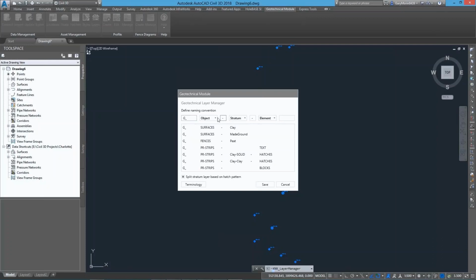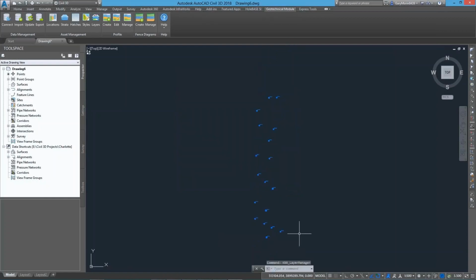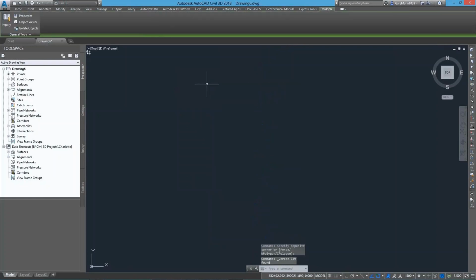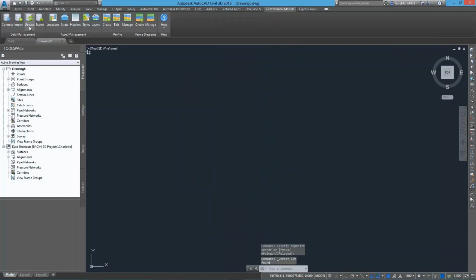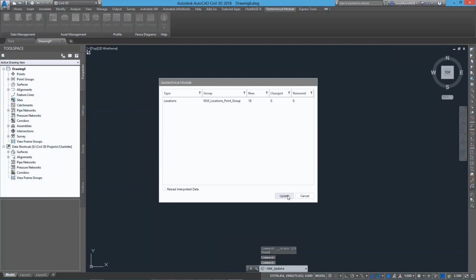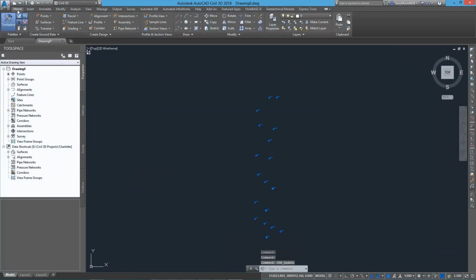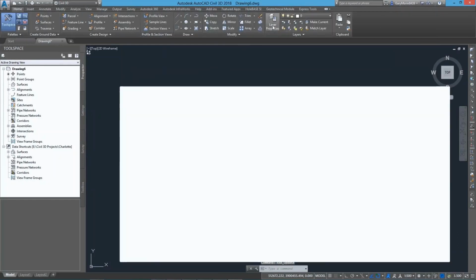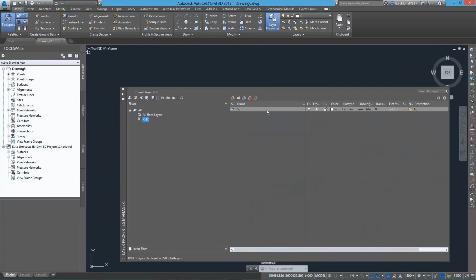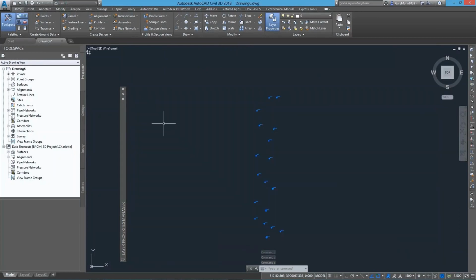So here, for instance, I'm going to start off really simplistic. Let's have a prefix for all my geotechnical layers. And in fact, I'm going to tell it don't bother doing anything else. So we're going to put all of our geotechnical data on a really sophisticated layering system called G underscore. Okay, so that's what my CAD manager insists, that all geotechnical data has to go onto a layer called G underscore. Wonderful. There we have it stored that way.